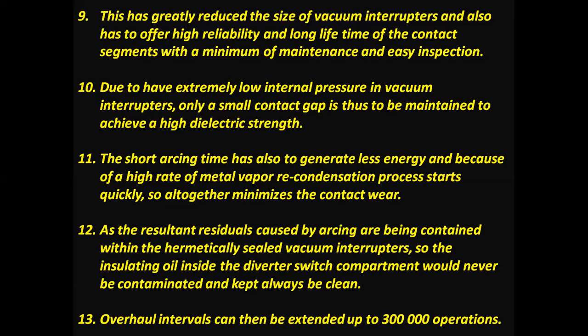As the resultant residuals caused by arcing are contained within the hermetically sealed vacuum interrupters, the insulating oil inside the diverter switch compartment is never contaminated and is always kept clean. Overall maintenance intervals can then be extended up to 3 lakh operations.